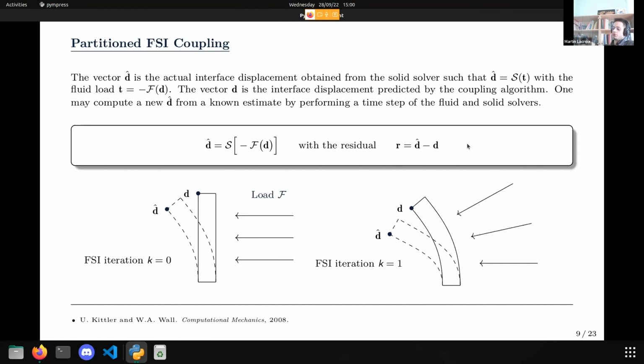The load that you compute before and after remeshing is not exactly the same, because the topology of your mesh may change. So the interpolation that is obtained from your shape functions will change too, and you will change this load a bit, and so the displacement, and so the residual will converge slower if you remesh more.